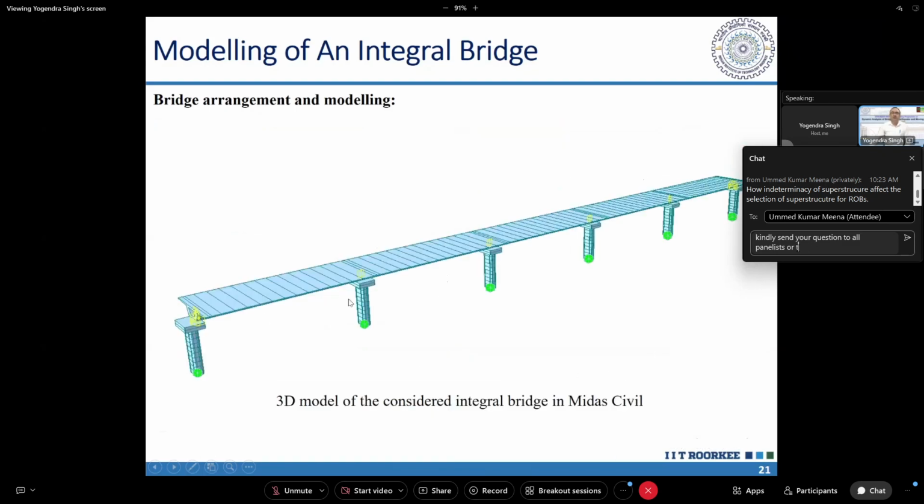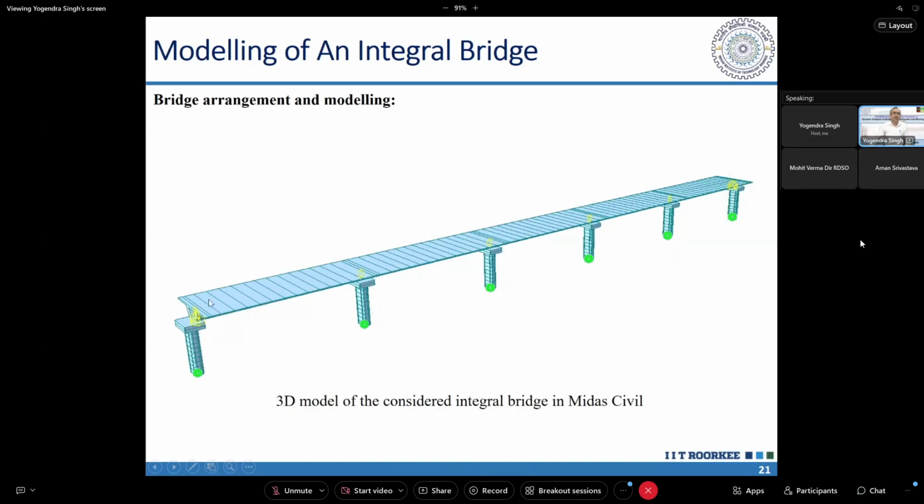And it will look something like this. So I have shown here the extruded view. Here the superstructure is modeled by a single beam element. And why do you see these transverse lines? These are because I'm showing you the extruded view, but actually this is just a line which I have not shown here. Similarly, these piers are also just lines. So what you see as these different elements, actually the pier has been divided into a number of frame elements. That's why you see these lines. So don't think that I have used shell elements or any other element here.